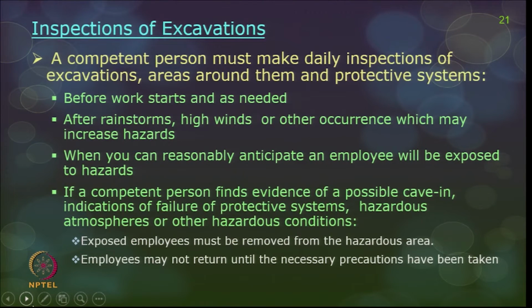Okay. Examples for all these dewatering techniques, for temporary and permanent ones. Temporary, you can think of easily some pumps and so on. For permanent measures, you can think of diaphragm walls, or maybe you can think of well point systems. Okay. Well point system is very good for temporary means of removing water from the construction site.